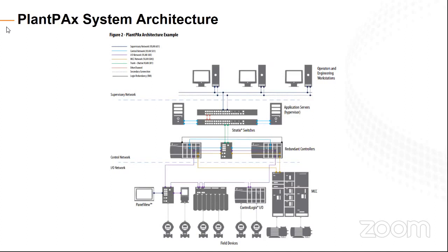As part of the documentation on the architecture, we're looking at now not just the controller set. So we're not concerned only with the controller and the IO. We're also looking at the networking pieces, the software that goes with, and how that ties in, including the power side of it. So we're going to be talking about the VFDs, the motor control centers, the field device implementation, all of it is documented as part of the PlantPAx system. So like I said, we're looking at it from a system level, not just the core products that we usually see.